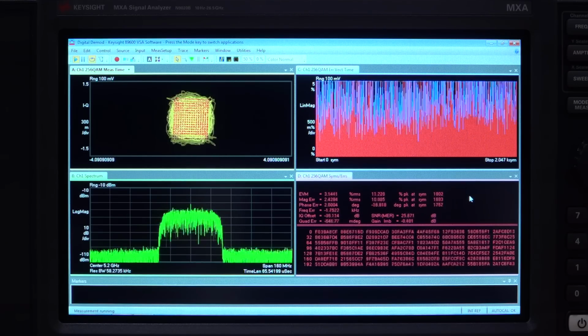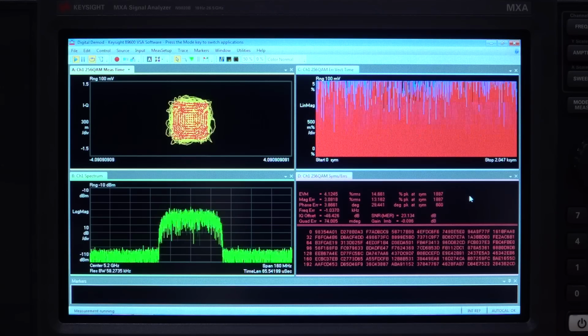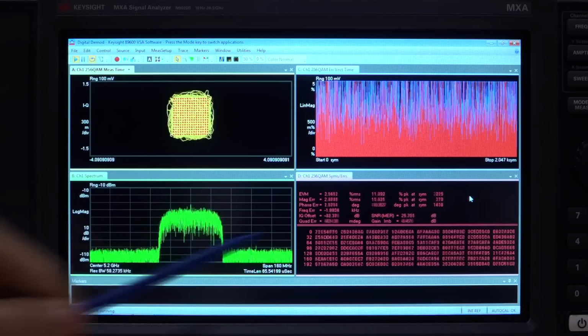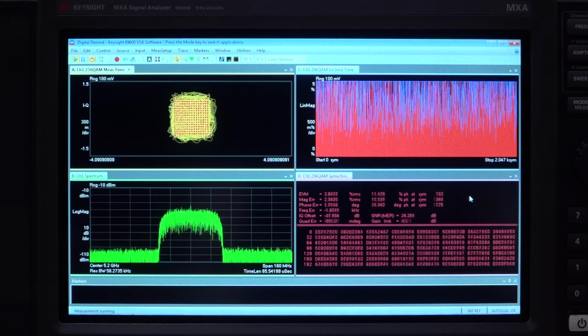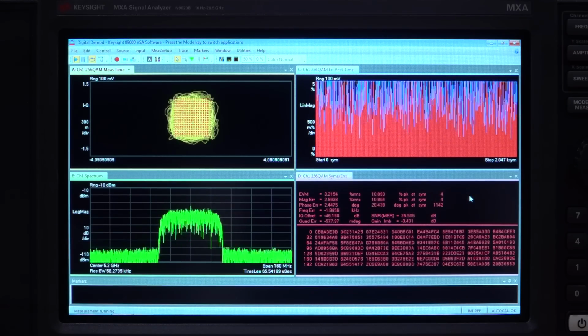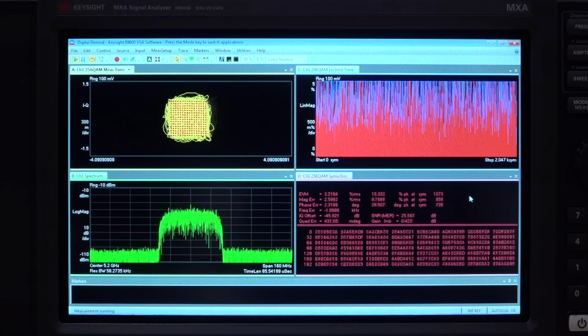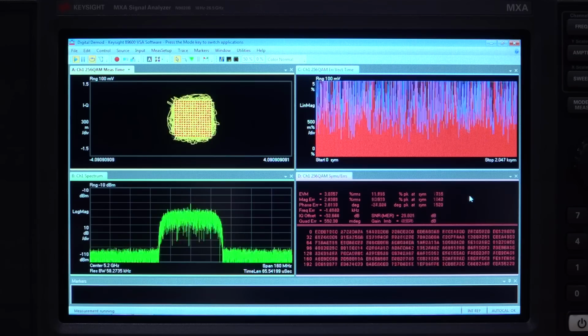But because I can move the carrier frequency of the arbitrary waveform generator, I can actually move this constellation anywhere up and down up to 500 megahertz away from my LO, and then therefore I can move it out of the band of the LO and create a superheterodyne system, and we can see what happens with that. So let's go ahead and try it.